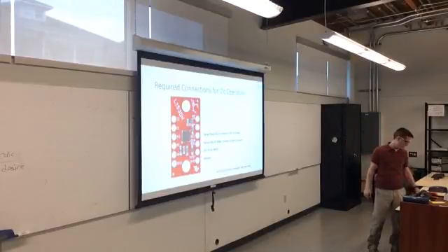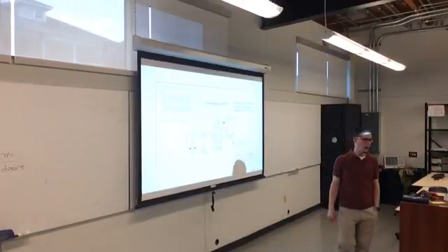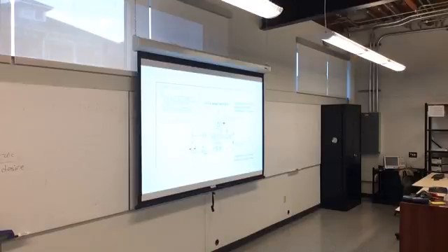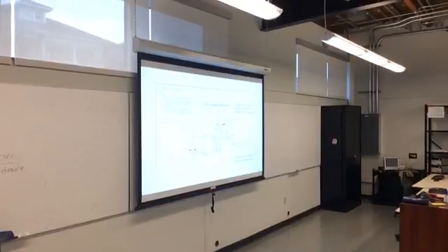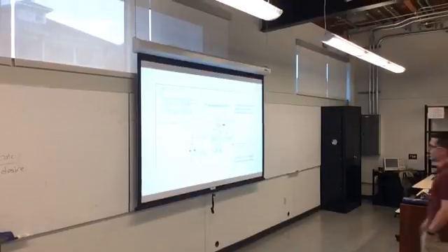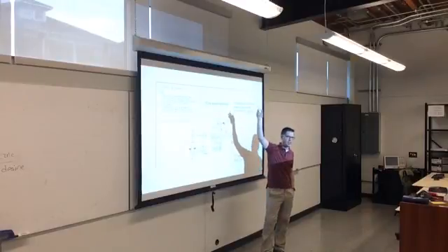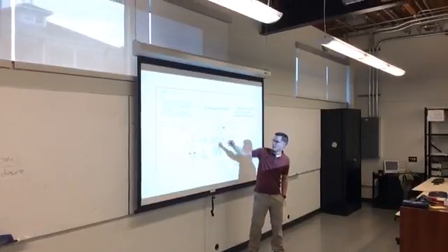The chip select line is naturally tied to high, which means that if you're doing SPI, it's naturally sort of inactive, and then when you pull it low, it becomes 0, you can talk to it. That also means that by default, this device is in I2C mode. So whenever chip select is high, it's in I2C mode. And they have already given you the pull-up resistors needed for the clock and data lines. So you don't need to add those. That's actually really convenient. It's less stuff.